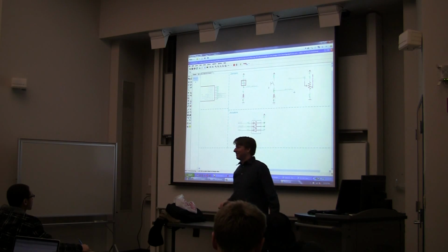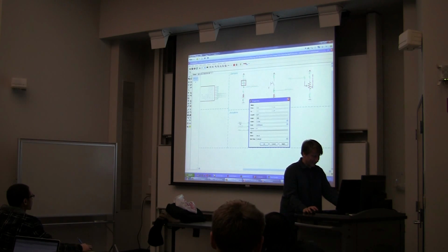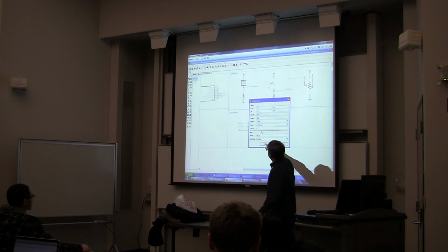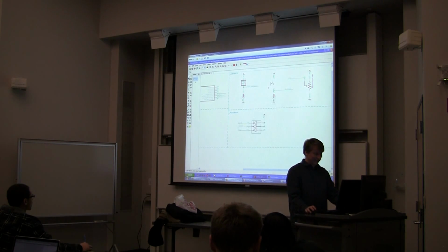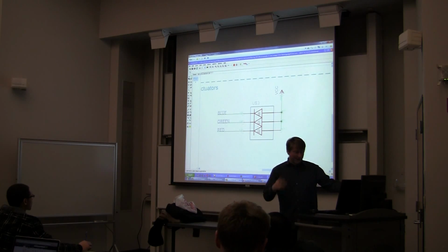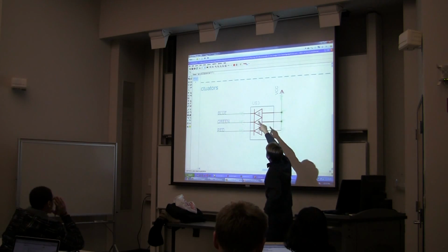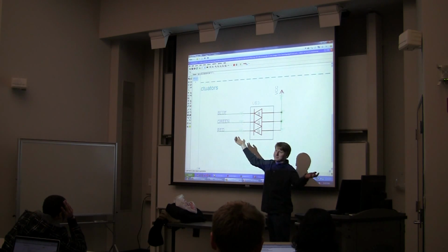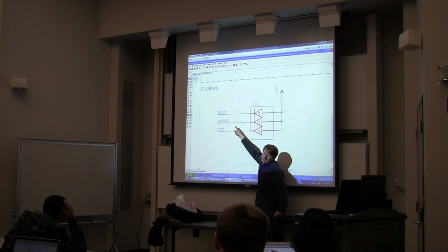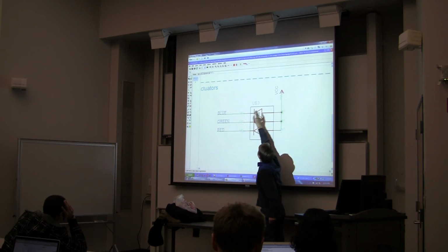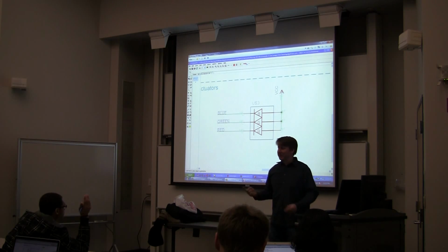Yep. So did you do the not bar? The not bar. You use an exclamation point. So it's not blue. It's exclamation blue. Doesn't mean it's exciting. It's not Spanish. It's a logical not. And the reason we have this is because if my microcontroller outputs a high on that pin, it will be VCC on both sides, and no current's going to flow. So we say it's off. And then the asserted state is low, so that when I assert it, it's going to be blue. And then I have 0 volts here and VCC here. Current's going to flow, and everything's great. That's what the not's for. Yep.